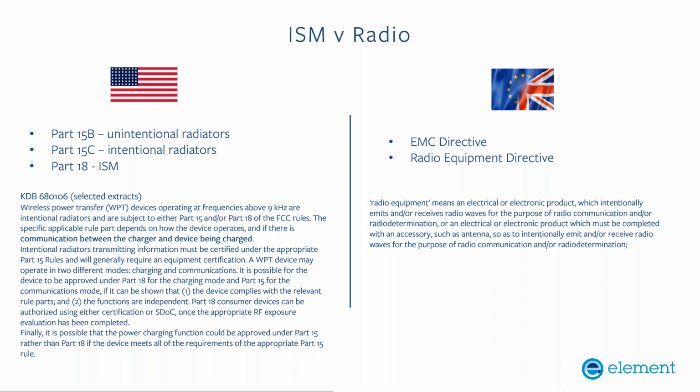I contrast that with the European situation. When I say European, I'm talking about a mixture of CE marking for the EU and UKCA marking in the case of the UK. Both of those regulatory requirements are the same, but slightly different regulatory requirements since the UK left the EU. And typically, ISM devices are covered under the EMC directive, and wireless devices are covered under the Radio Equipment Directive.